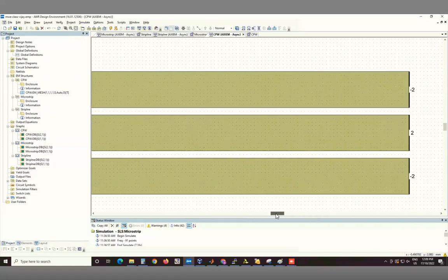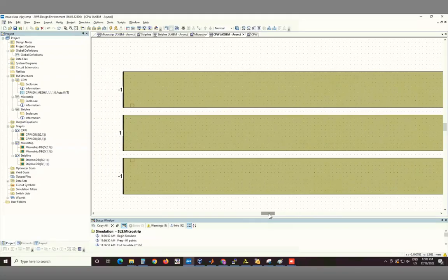But you have to do this at some regular intervals along the length of the transmission line. Otherwise, you solve the problem here, but then these two potentials can drift. So the higher the density of these things, the better. But then again, in a simulation, you have to worry about the simulation time. In your real setup, you have to worry about how much you can realistically space them. I have made them as 50 micron squares, which is kind of small compared to the size of the holes one typically drills. So maybe better to make it